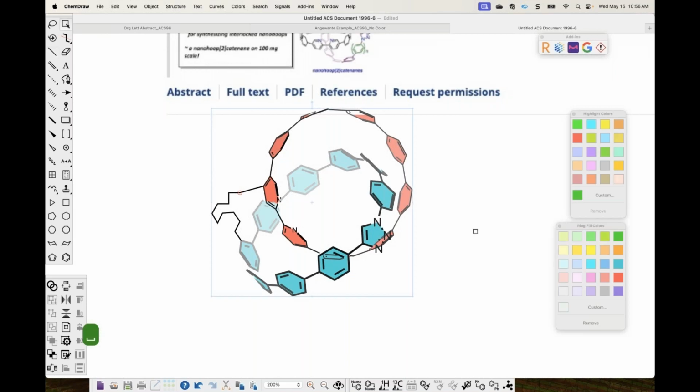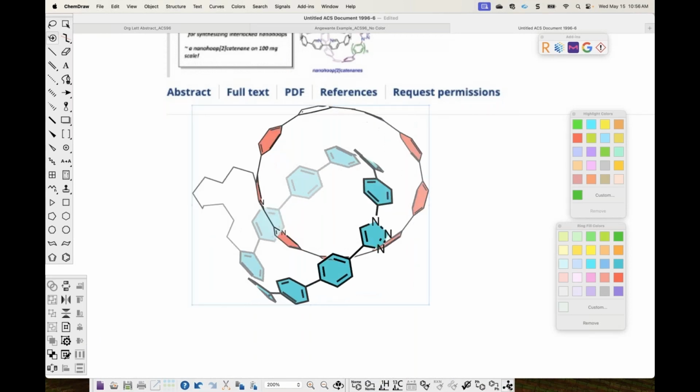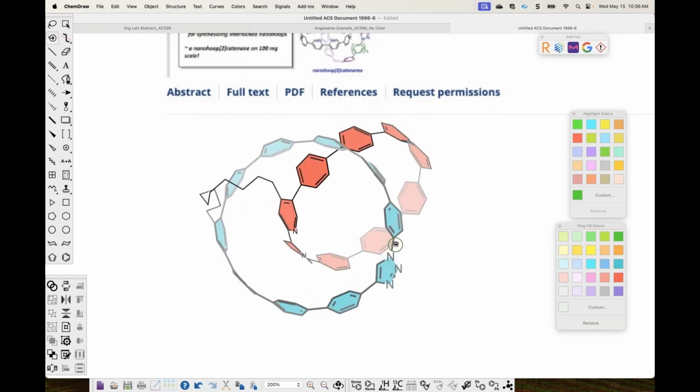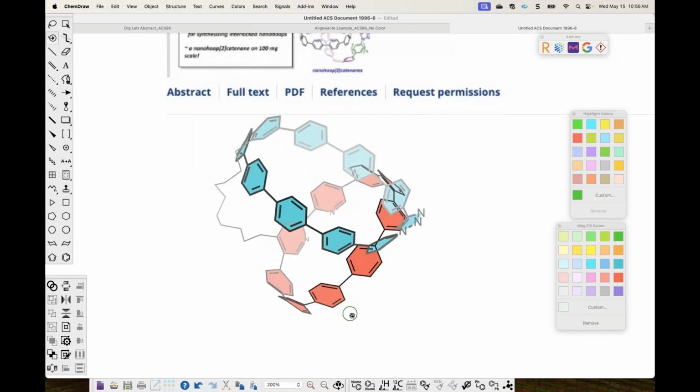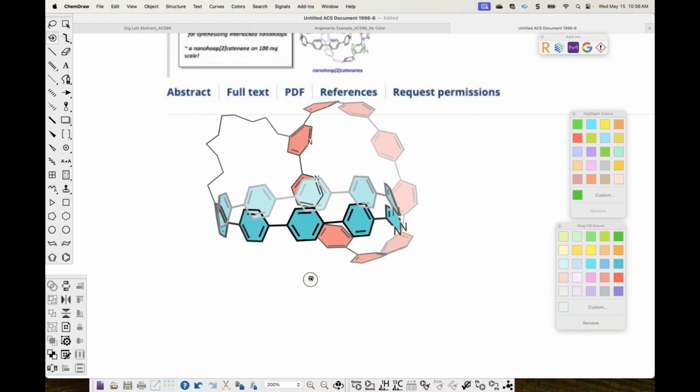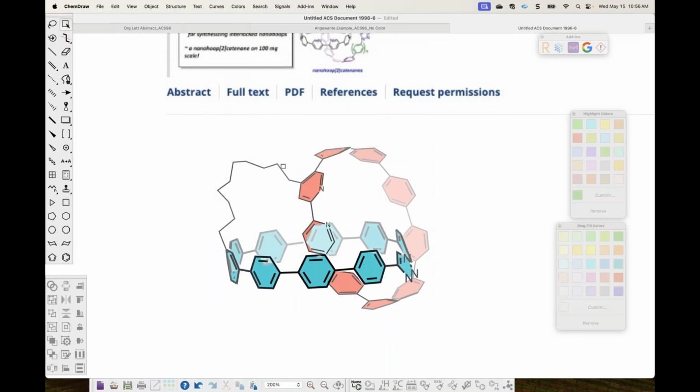And now when we select it, that's taking both of these cycles into account. And I can do 3D clean, and it will start to make these look a little bit better in terms of their connection. So you can use this then in your graphic representations in your abstract. Once you get the orientation that you like, you can just go ahead and delete, and you'll have something that you can very easily and quickly put into your presentation.